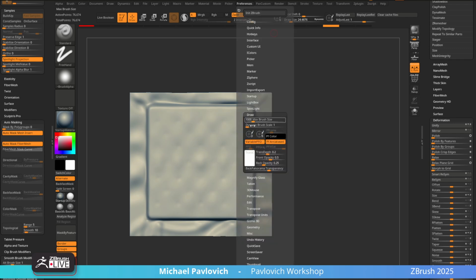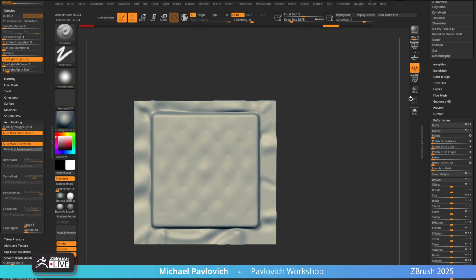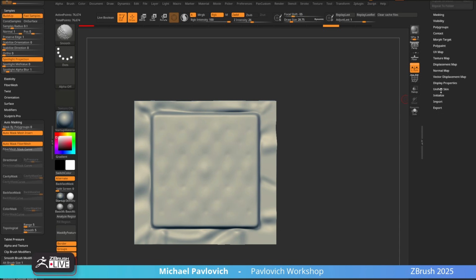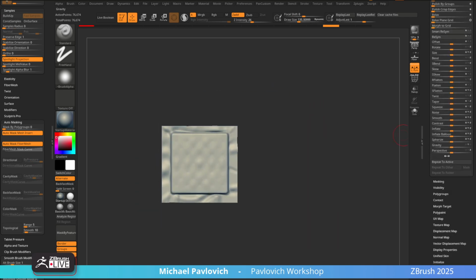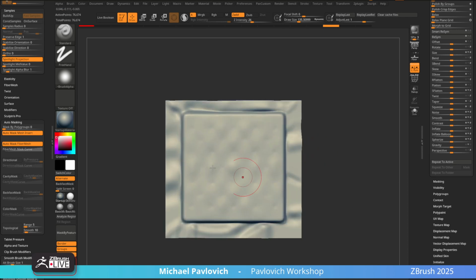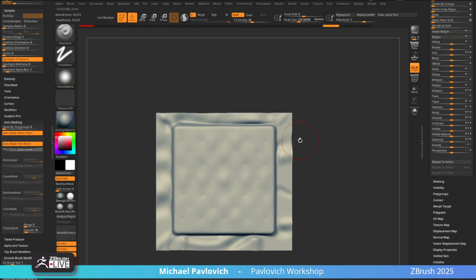Preferences, draw, changing your max brush size and dynamic brush scale is an option. Or what we talked about earlier when we brought in the Marvelous avatar: when you import that, it will change your export scale here from 1, I guess the default's 1, to 977 or whatever it needs, but your brushes will still behave normally because under the hood it's making your huge Marvelous avatar ZBrush scale just to make everything compatible.